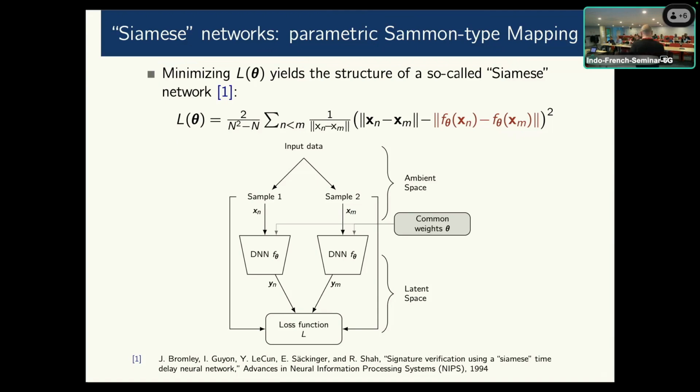And I'm sure that if you have any intuition about the physical layer, you know pretty well that even if you have two channel measurements which are measured more or less in the same situation, like the same location, but you do the measurements twice, and then you take this very long CSI vector and subtract them from each other, the difference will not be close to zero. So in fact this is an issue, because all the methods I have presented so far rely on the fact that this distance is meaningful, but in reality it's not.